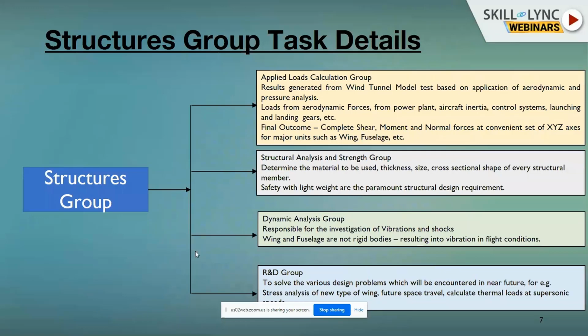You design some elements and you get the loads for that. Even that we do manually also. For example, a wing to fuselage is a cantilever beam. So the weight of the wing, UDL, I'm going to say uniformly running load, which is stored in the tanks. Then you apply a certain set of loads. You analyze it through pen and paper.